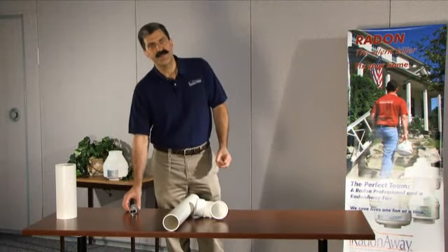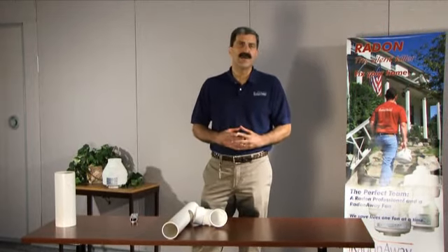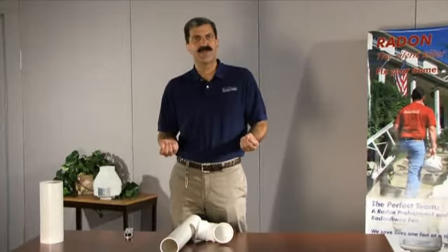Once we've determined the equivalent length of the system, we can now take a look at what the pressure loss is inside various types of pipe at different airflows. And from this, we can build a chart which will allow us to then answer that question. Is there a significant pressure difference or pressure performance difference between 3-inch and 4-inch pipe?